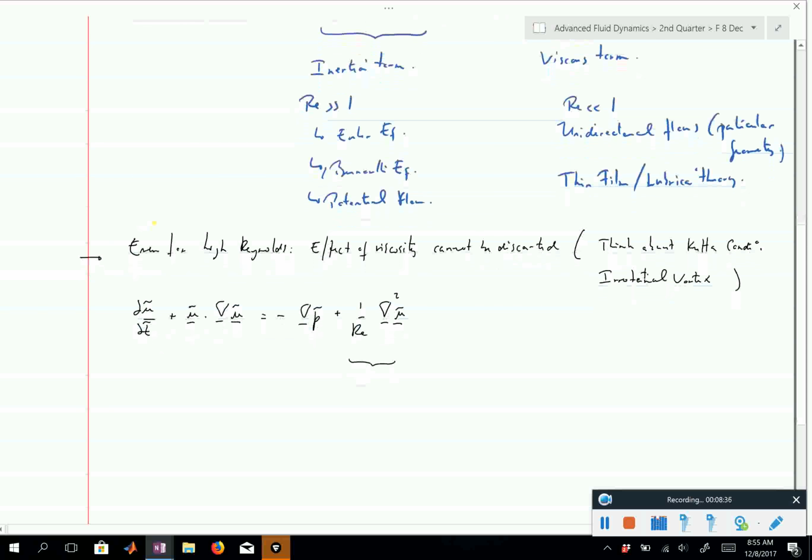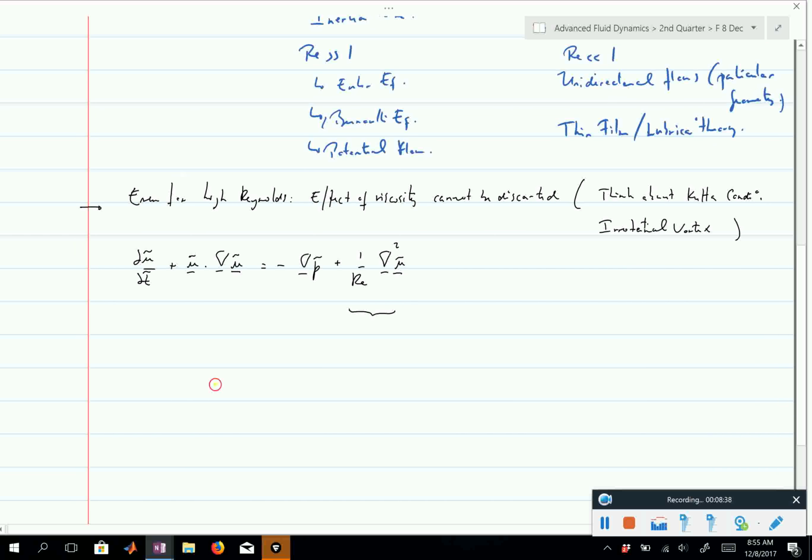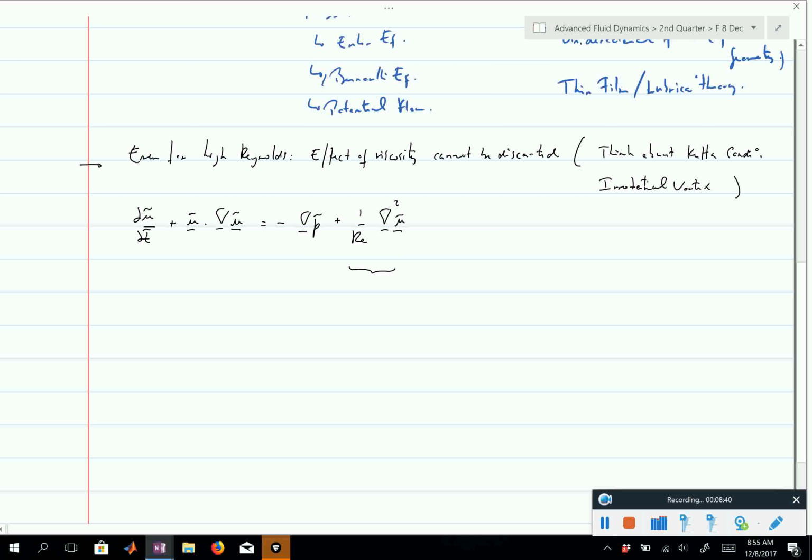But so when you're doing ideal flow or potential flow, essentially what you do is stuff all of the effect of viscosity in regions which have no thickness, either a point or a layer. And those in reality have a certain thickness, and those are called boundary layers. So you'll see it just here.